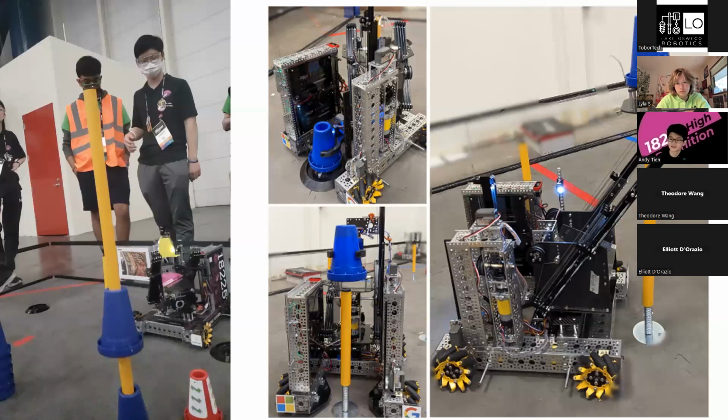The last one is that the extender could accidentally drag the pole down all the way. That is certainly a point of failure, and we mitigated that by wrapping the delivery guide all the way around the slides. That way there wasn't much space between the slide and the guide board, and that prevented the pole from getting caught inside the guide board. And if the pole was caught under the guide board, simply pulling back would capitalize on the elasticity of the pole, and the pole would fling back into the correct position. So now we're going to go into our states robot.